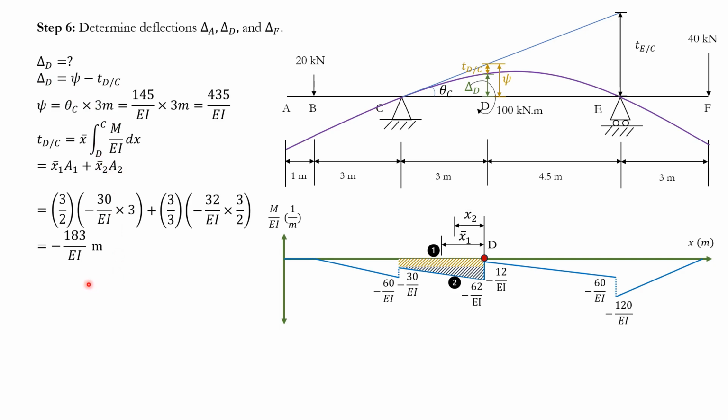One very important thing here is that for finding deflections, we can actually see how they look. So although you get this positive value, which doesn't really mean anything, you get this negative value, which again just means something else. It just means that the point that I have here is below the tangent. Okay, good. That's all this negative sign means. So when you put these values into the equation, just keep that in mind. Go with the diagram. Don't go with the negative and positive sign because they don't really help us. In fact, if you put them with signs, you're going to end up with the incorrect answer, right? So in other words, always go with absolute values. Don't go with negatives at all.